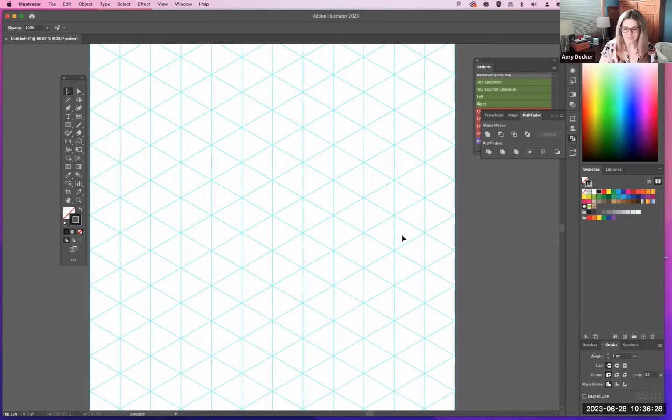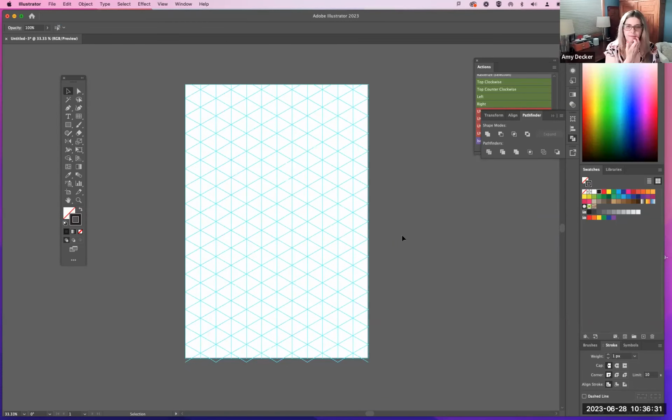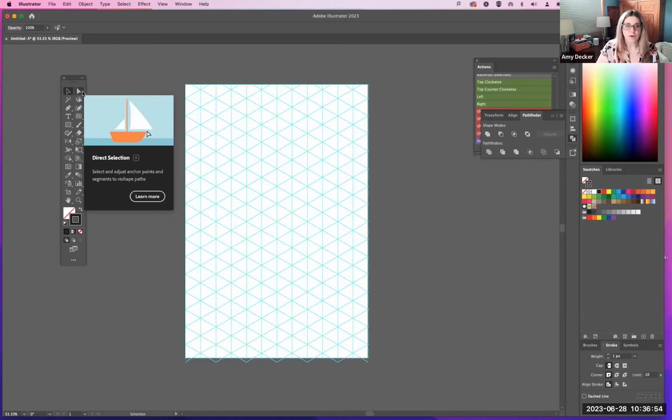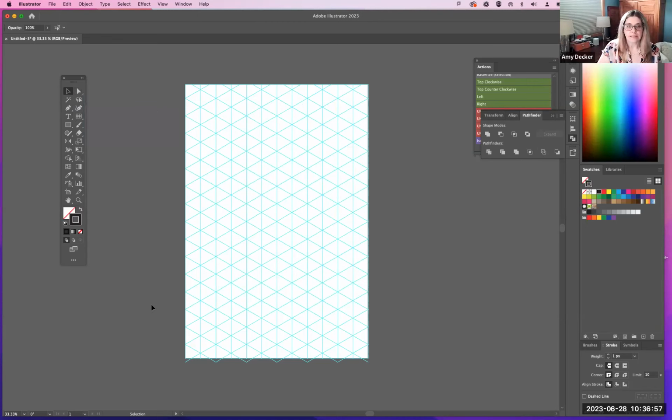Okay, are you all with me? Give us a minute. Any other questions before we move on to the next step? Yeah. How did you clean up the lines? Once you select them all, you go to Pathfinder, outline, and you outline them. And then once they've been outlined, you use your direct select tool to delete the lines that are on the outside of the artboard. Okay. Any other questions?